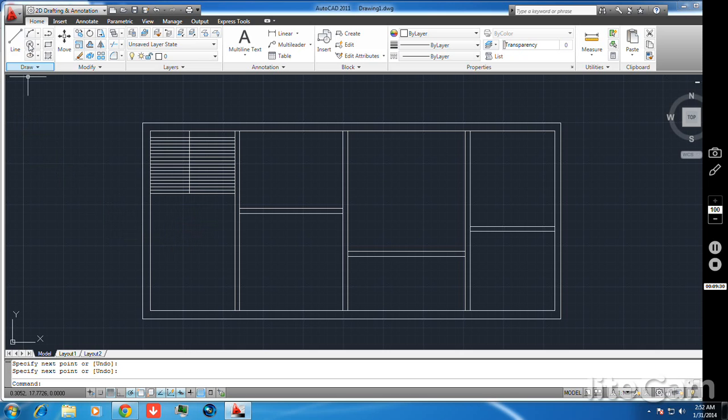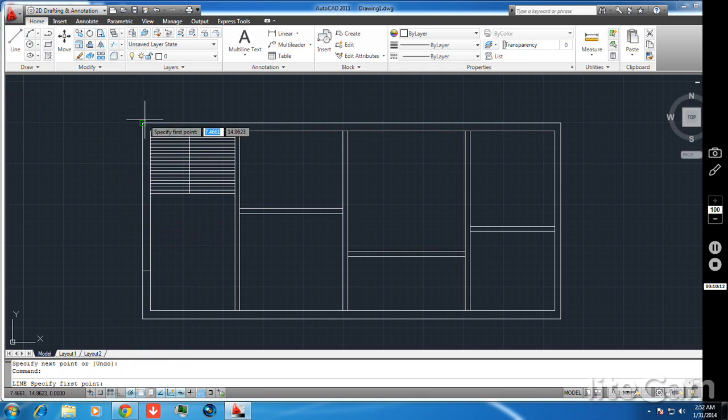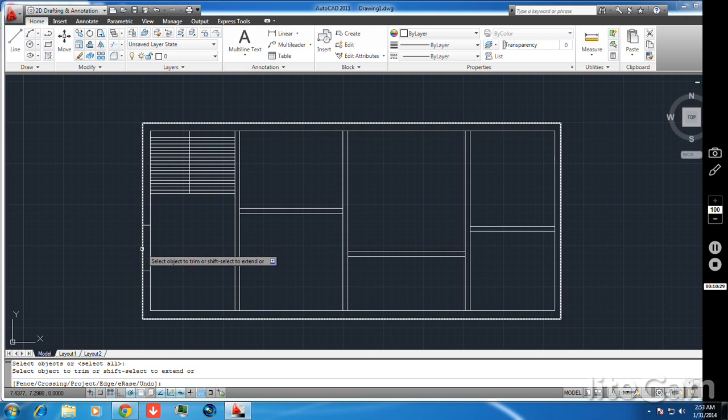Now I want an open gate here, so I close this portion. Oh, it is not a proper line. I create a rectangle from here. Sorry, undo is the command with which we can erase an object. This one line, I want to cut that portion, because this portion is for the entry. Now I use the trim command: select trim, select, enter, and cut the portion.